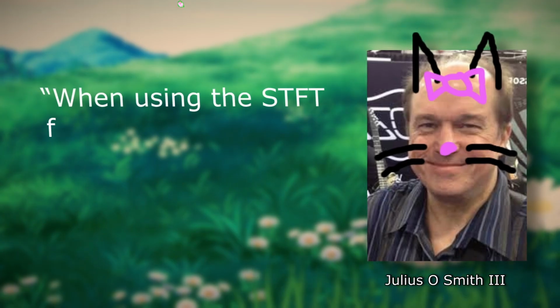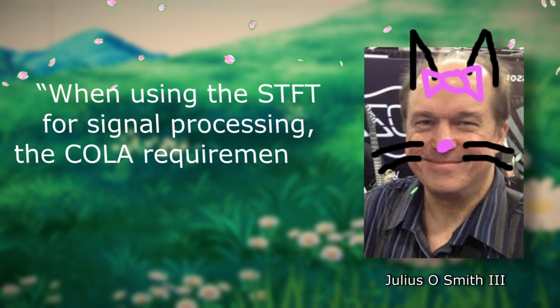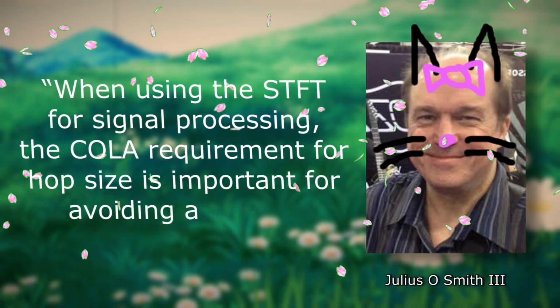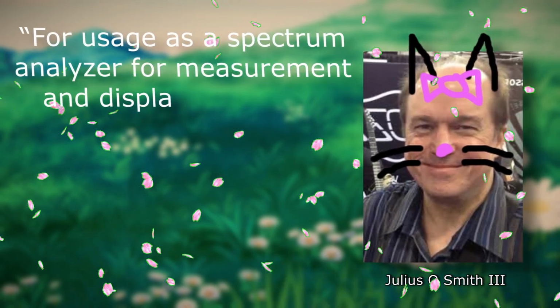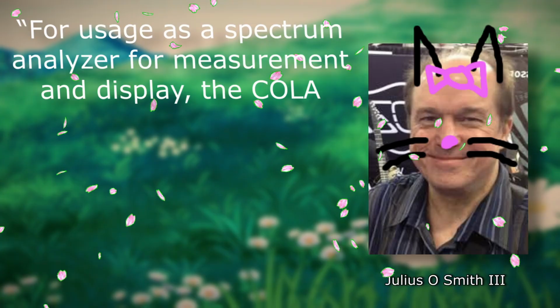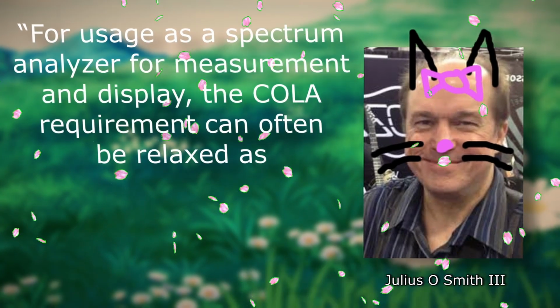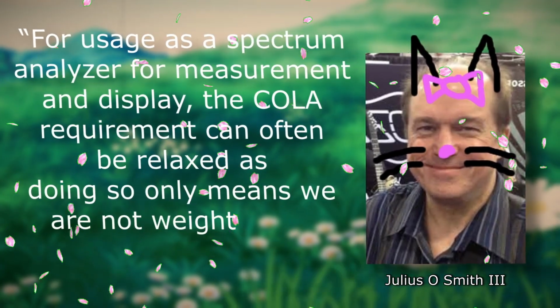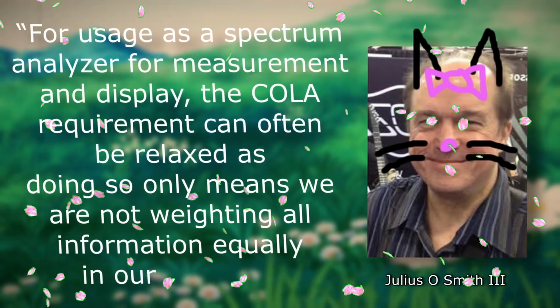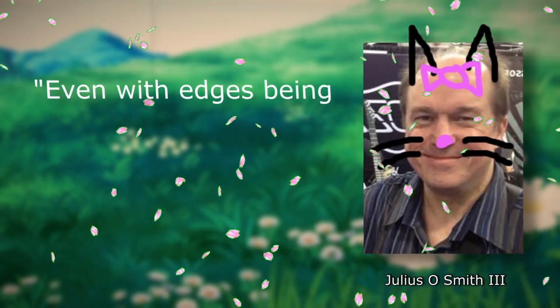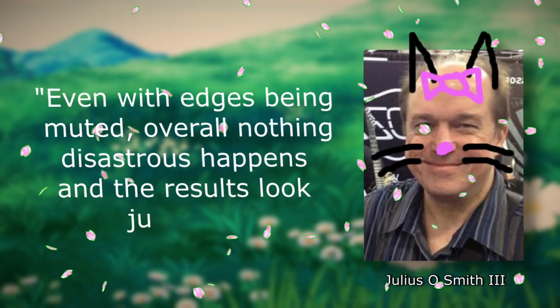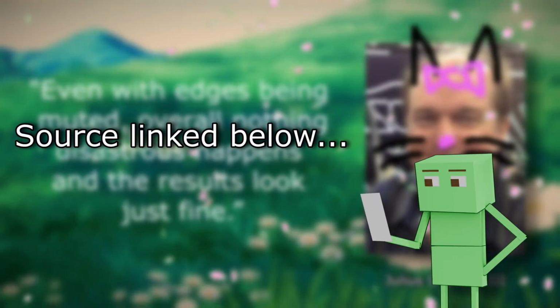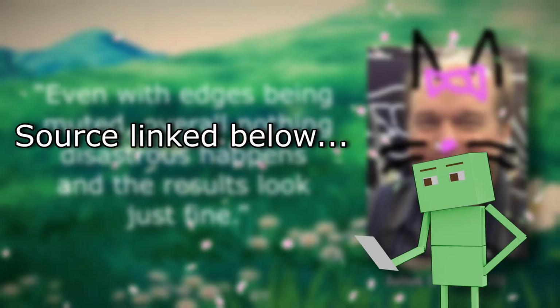When using the STFT for signal processing, the COLA requirement for hop size is important for avoiding artifacts. For usage as a spectrum analyzer for measurement and display, the COLA requirement can often be relaxed, as doing so only means we are not weighting all information equally in our analysis. Even with edges being slightly muted, overall, nothing disastrous happens and the results look just fine. And we're already on page 4 of this script, so we're going to pick a hop size of half the frame size and call it a day.